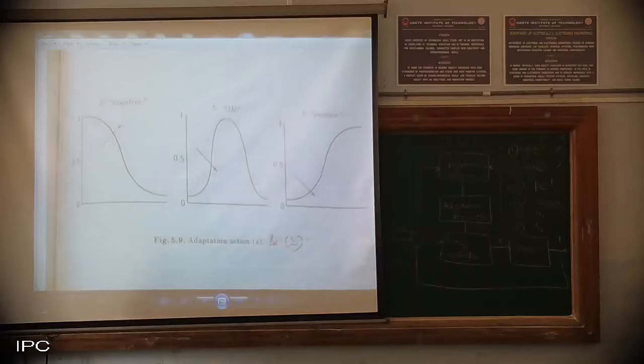By changing this, suppose that our answer would have been here. Now as it has been bulged, it will come on this part, so our answer will change a bit. Here we are going to modify the membership function of the error. We have increased the value of the error membership for the negative values. By increasing this, we have changed our output. So this is what adaptive action A and B are.